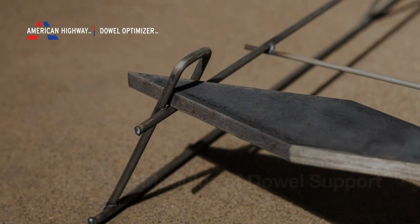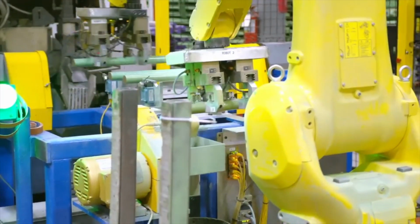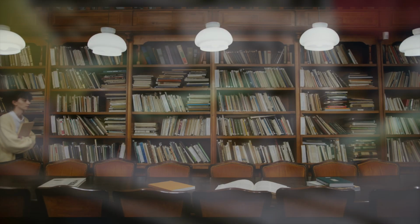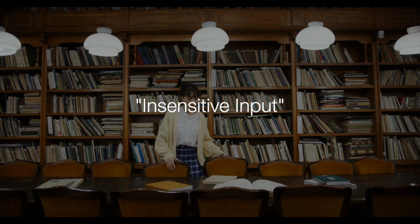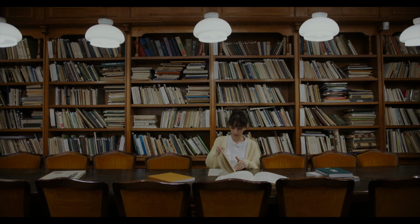First, resolving the modulus of dowel support. One of the most persistent questions in dowel design relates to the modulus of dowel support, a parameter long assumed to be 1.5 million psi per inch. This estimate was widely accepted in part due to its inclusion in concrete pavement textbooks, where it was considered an insensitive input. However, this generalization fails to account for dowel shape and other factors.